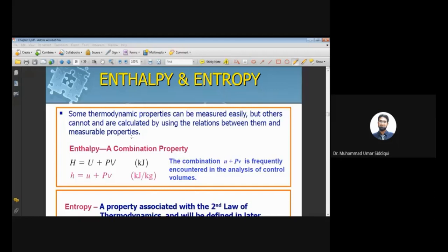We call it enthalpy. So enthalpy is basically what? It's the useful energy content of any fluid. And we understand that the useful energy content could be because of two reasons. One might be that the substance has a lot of internal energy, so its temperature is very high. But there is another possibility that the temperature is not high, but the pressure of that substance is very high. So water which is not at very high pressure, but whose temperature is very high, let's say boiling water, can do some work.